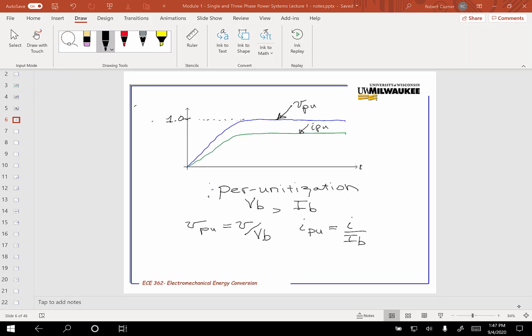Now the behavior we're seeing here, as far as these waveforms go, can really be divided into two parts. This part of the waveform is a transient behavior. This part here, everything has steadied out, it's reached its level and nothing's changed, so we tend to call that steady state. It's steady state behavior right there.